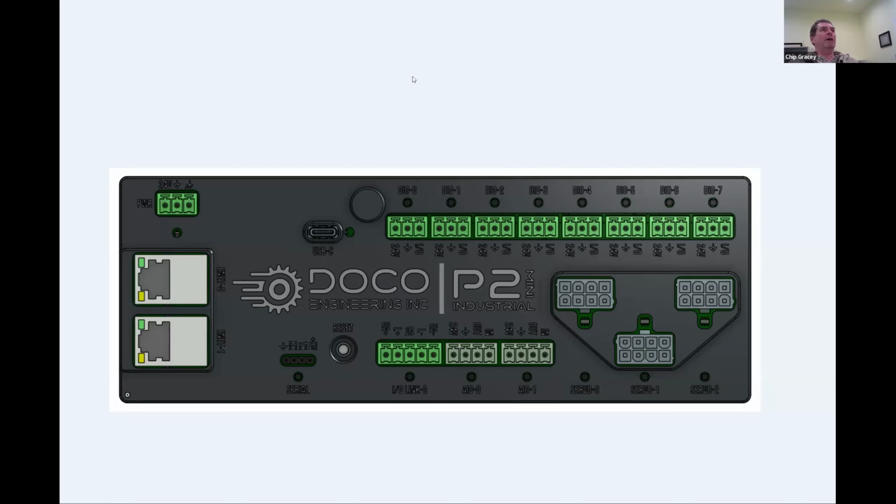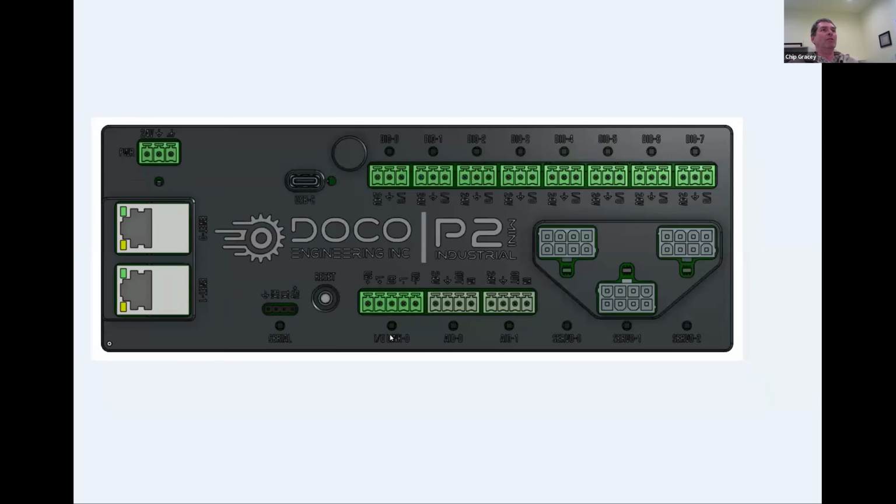But what I was going to show about this is there's this one little thing I had to do. You saw that in all these little holes there are those RGB LEDs, right? You send this 24-bit RGB data to the first one, then the next one, and each guy captures what he got, and thereafter he just relays what's coming in to the next guy. So it's not exactly like a serial chain where the first one you load winds up being the last one on the chain. The first one is the first one, and then each guy passes the next serial string. So it's like one wire in, one wire out. So it's a 4-pin device.